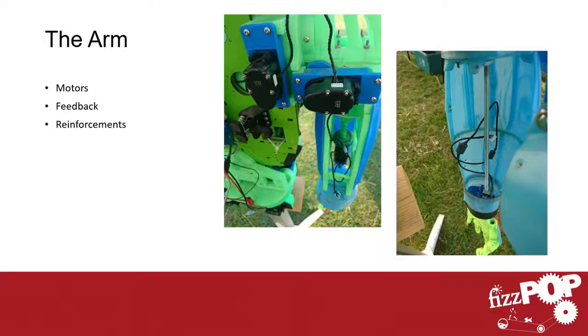And the only problem with this approach compared to the original approach is that if you look at the original instructions, the sensor was removed from inside the motor and placed directly at the joint. Because there is a gearbox between the motor and the actual joint, the position of the motor does not tell you what the position of the joint is. But ROS needs to know the position of the joint. The solution for that I have not implemented yet.